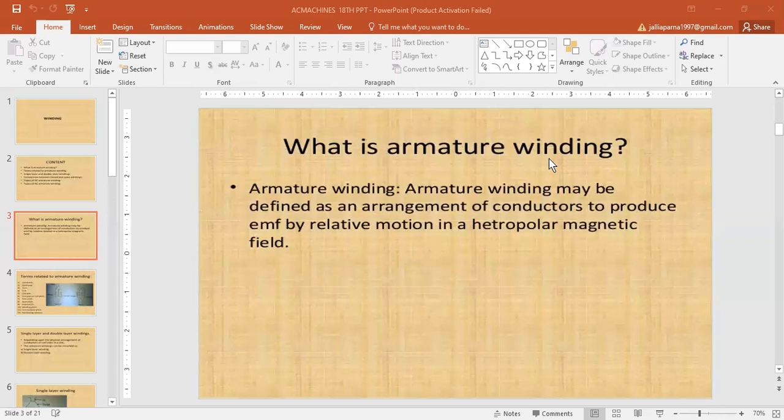In practice, coil pitches as low as 8/10 of a pole pitch are employed without much serious reduction in the EMF. Fractional pitched windings are frequently used to effect a substantial saving in the copper of the end connections and to improve commutation. Back pitch YB.